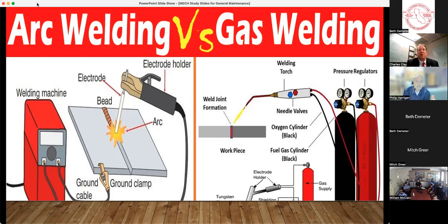On the gas welding side of it, you'll use flux in addition to the welding rod to make that seal. What's preventing the oxidation on the arc side is the flux that's being burnt off. As it goes through there, it actually keeps the molten metal from oxidizing. And the same way that you'll use for your welding rod, you'll use a flux material, which is in addition to this, you'll dip the rod in.